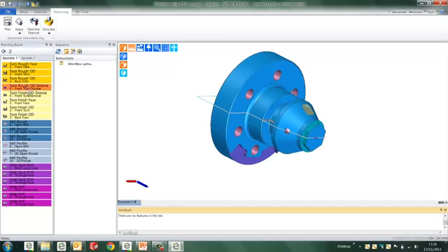Now there are certain elements of flexibility. I may wish to mill the part before I finish turn the part, and we can start to drag and drop, and we can reorder the process as we see fit. There are also elements of safety built into this to stop us making bad decisions. But first of all we'll see here I'm going to drag the rough mill up the tree, and I can influence the manufacturing order by doing this.